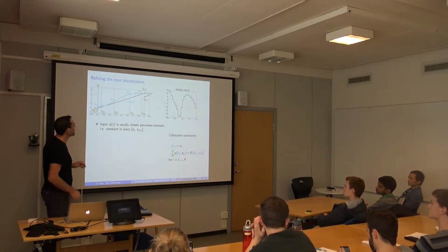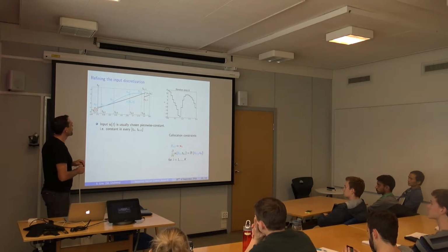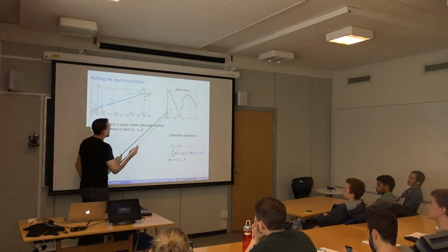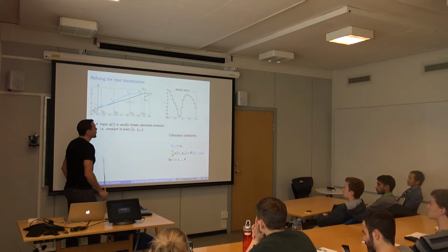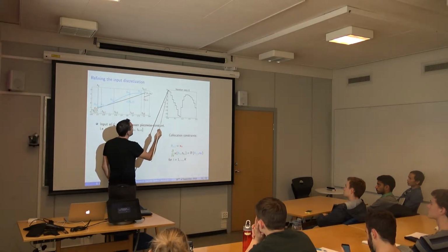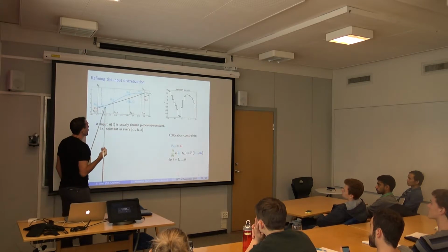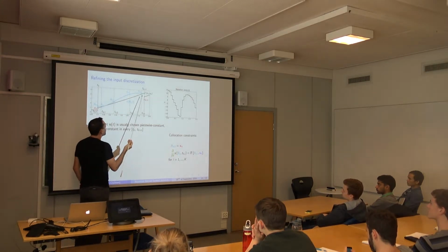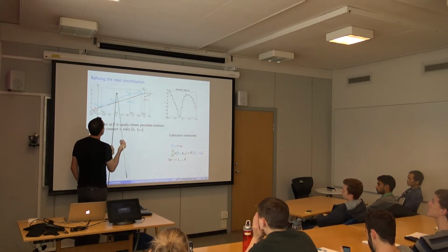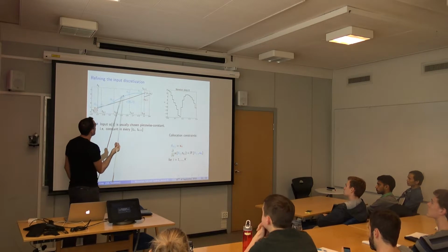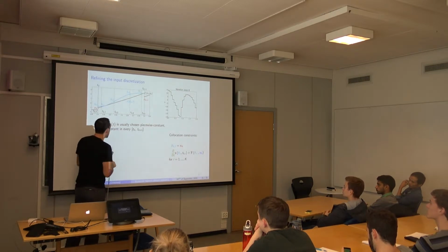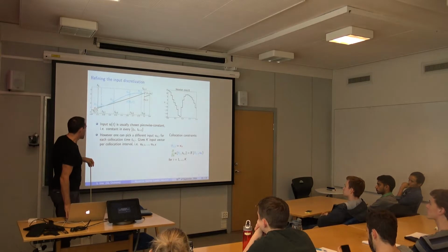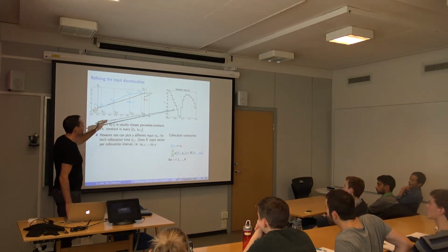Yeah, that's okay. Something that you can easily do in direct collocation, because we always discussed a piecewise constant input, but obviously you don't have to choose that. You can also, for example, imagine that in each of these time intervals you actually represent the input by a polynomial itself. And why not use a polynomial of this form, right? So then what would happen is that on every one of your time points here, you would have a different input, as opposed to having something constant throughout t_k to t_{k+1}. So you can easily refine your inputs and, for example, pin a polynomial on them.